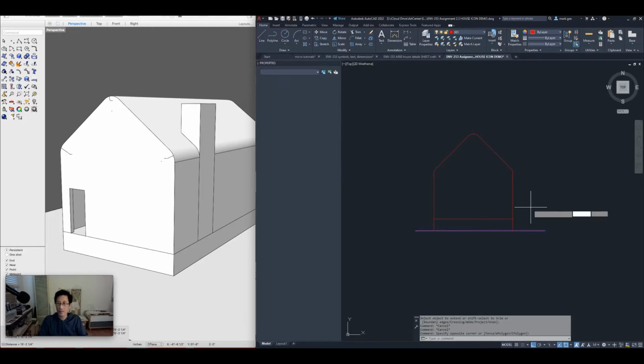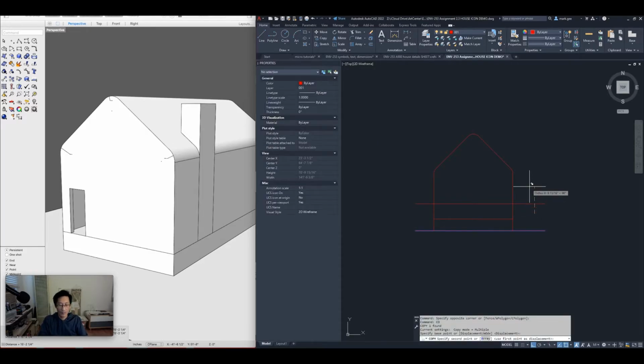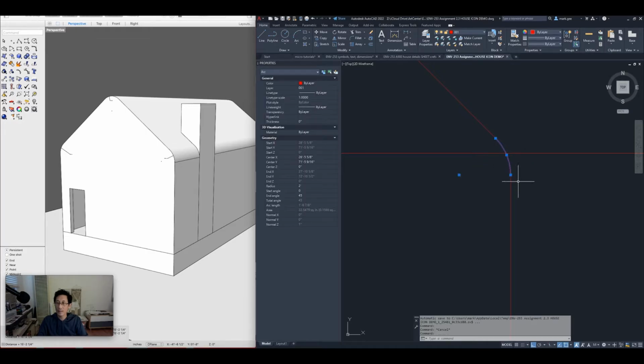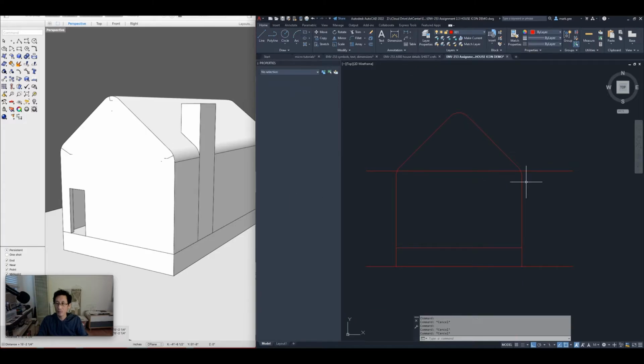So we'll copy this 15 feet to, and now again, 2.25, because that's just a faster way to enter it. So that's the line at which the endpoint here, the beginning of that curve, should be. So in order to raise everything, I'll use the stretch command, S,